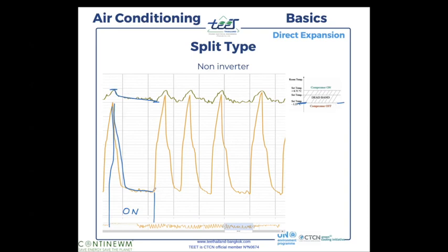So the compressor stops. When the compressor stops, of course, there is no more refrigerant fluid coming out from the expansion valve. So the temperature of the air supply rises. If the temperature of the air supply rises, the temperature in the room rises until it reaches this point, what we call the compressor on point, okay. And when you reach this temperature up, the system says, hey, temperature is too high, I need the compressor to start again. So between this line here, we have the compressor off, okay.